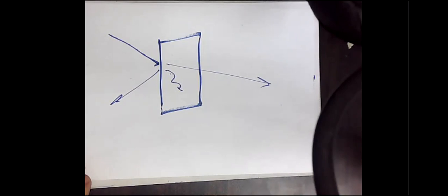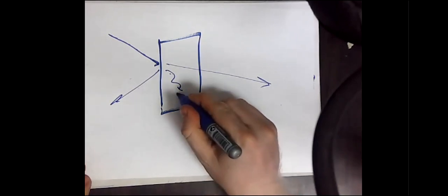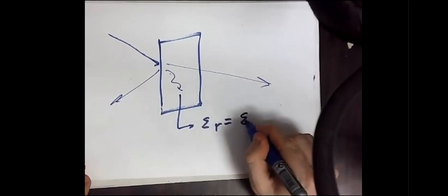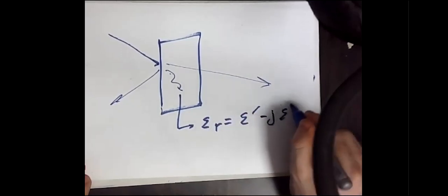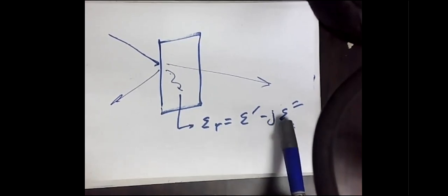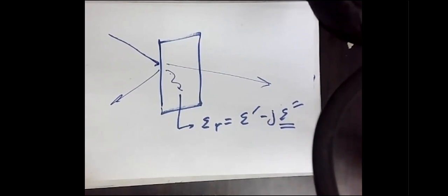in the medium. The source of absorption is to have epsilon_r equals epsilon' minus j epsilon''. Whenever you have this epsilon'' effect, you have an absorption effect, or what you call in your microwave and EM course, the losses. Herein, we call these losses the absorption phenomena.